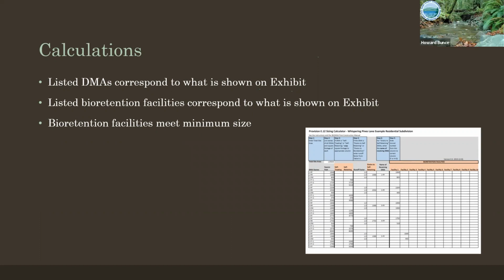And a second question, is there a life expectancy for the growing media in a bioswale? In other words, does it self-compact over time with inundation and have to be replaced? Good question. We will get into that under soils, which is coming up. And the answer is really no. The idea is that the tilth of that soil should improve over time because of biological activity. And there are plenty of bioretention facilities that are 30 years old or more that are performing just fine. And that's really the key.